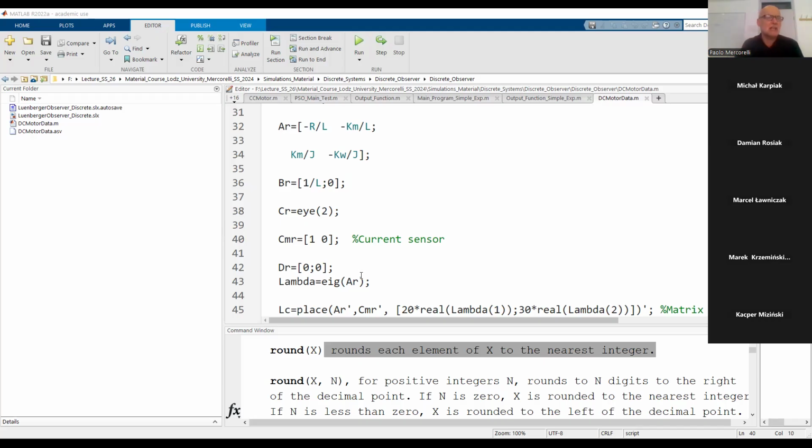The possible modification is exactly the Kalman filter. With the Kalman filter, even though I don't know the model perfectly, even though the measurements are affected by errors, nevertheless we find a good compromise to estimate, in the best way in accordance with the cost function, the state which I don't measure, and also, in the best way, the state which I measure.